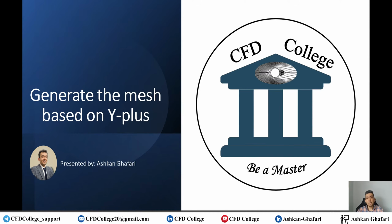I'm Ashkan and in this video I'm going to talk about how we can generate the mesh, the grid, based on Y plus in ANSYS Meshing. So in many projects, actually in most of them or all of them, I think, I mean the turbulent flows, we need to think about Y plus, the turbulence model, wall function, and y plus. So we basically need to generate this mesh, the grid, based on the y plus that we want.